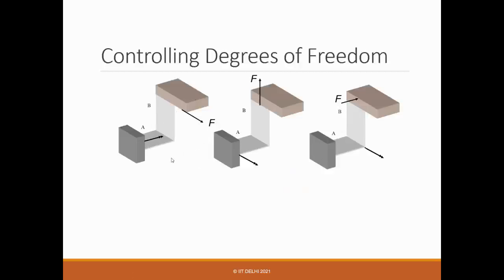If you take any visiting card with you, or any small piece of paper, it looks very simple and looks very fragile, but what you have to understand is you just try yourself and you will find that there are 3 degrees of freedom and 3 directions are constrained, and those are basically the motion in the plane that is constrained.